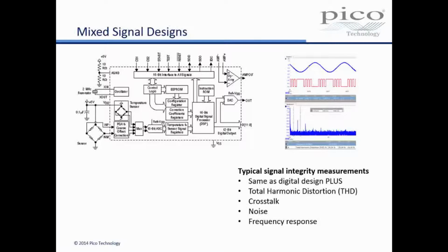A conventional oscilloscope with 8 bits vertical resolution delivers 256 levels, which is fine for timing measurements, but for mixed signal designs the required oscilloscope specifications are more challenging. Designers need to make measurements with higher resolution and improved dynamic range.